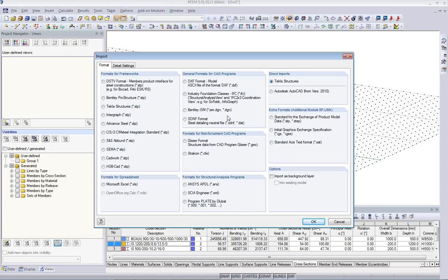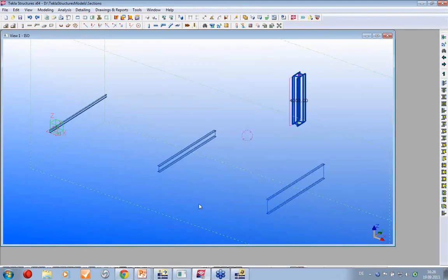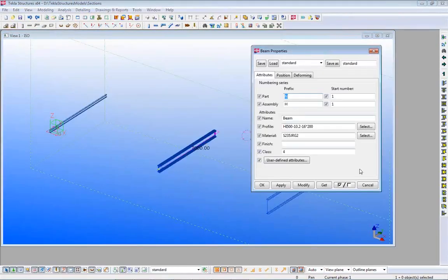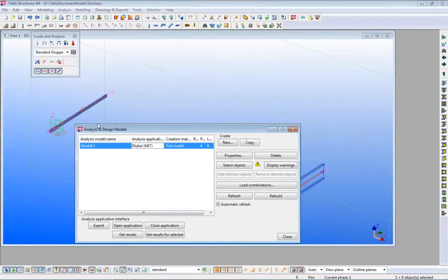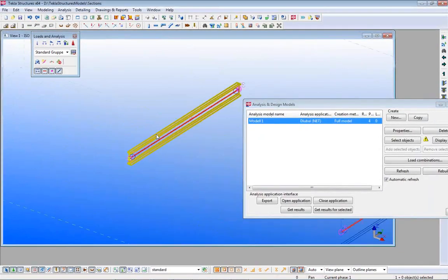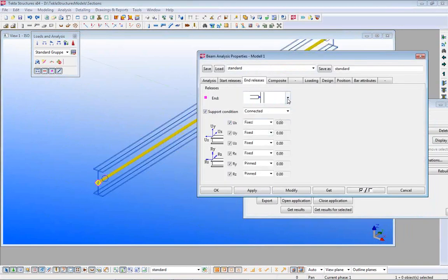Can I use springs as a release in Tekla? As I said, in Tekla you need to have an analysis model, where you can set up releases and also spring constants. They can be, for example, a spring. And if you have this spring constant, then we also import this spring constant inside our analytical model.